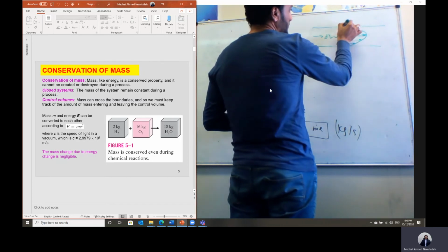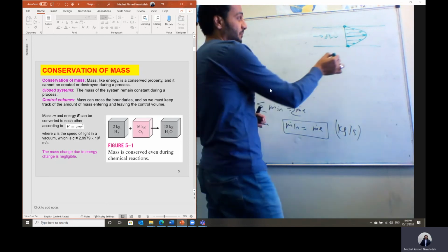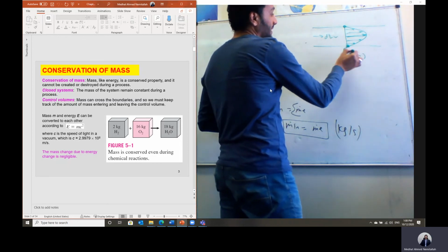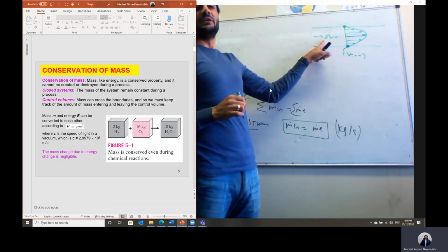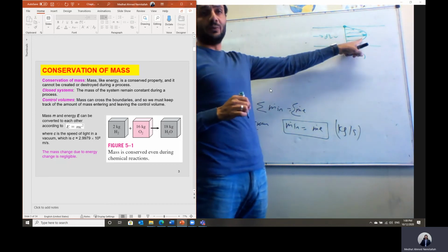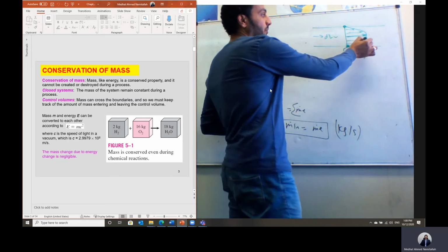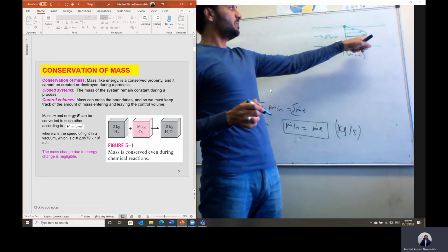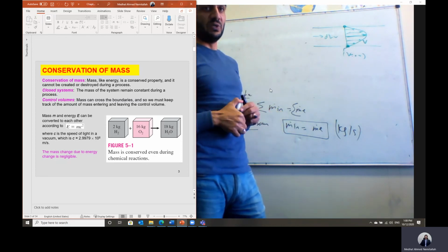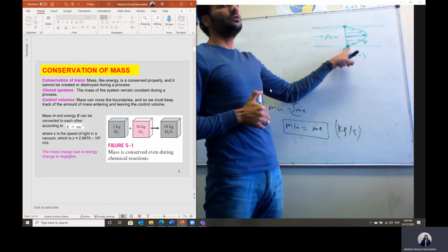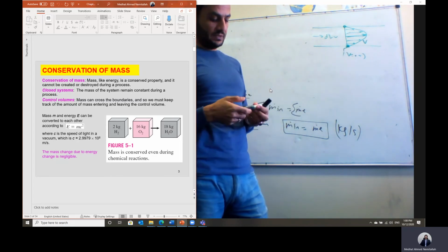And the velocity at the interaction with the wall, due to the no-slip condition, should be equal to 0. So the velocity of the flow inside the pipe is a kind of parabolic distribution at any cross-section. This will be the distribution of the velocity of the flow. The velocity should be maximum at the center line of the tube because the friction is minimum at this point, and the velocity due to the no-slip condition at the wall will equal 0 in this case.